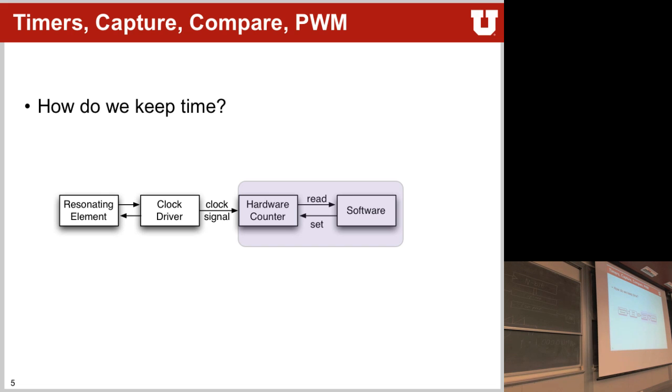And now it's really easy to change your duty cycle on this particular signal, because all you do is rewrite this particular register to a new number, and that way you can change the duty cycle from 0 to 100%, depending on what you need. Any questions? No?